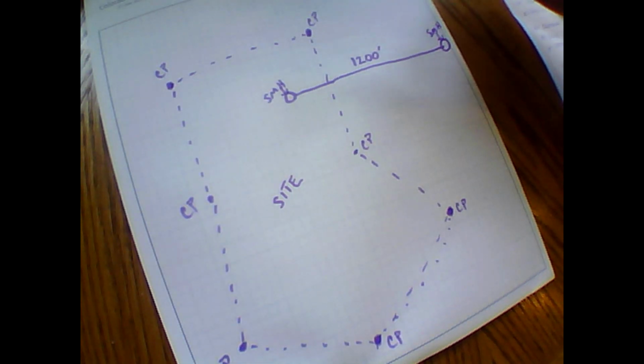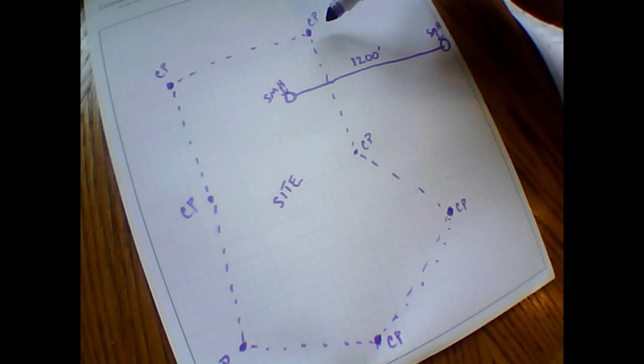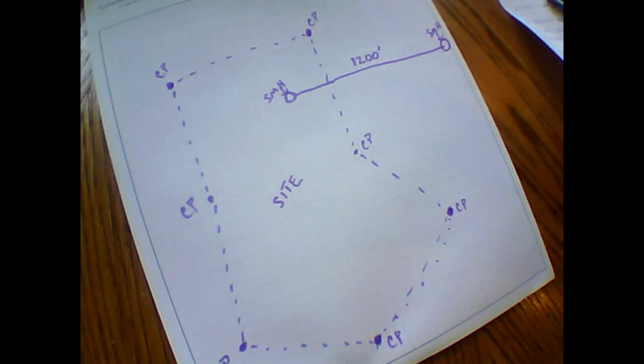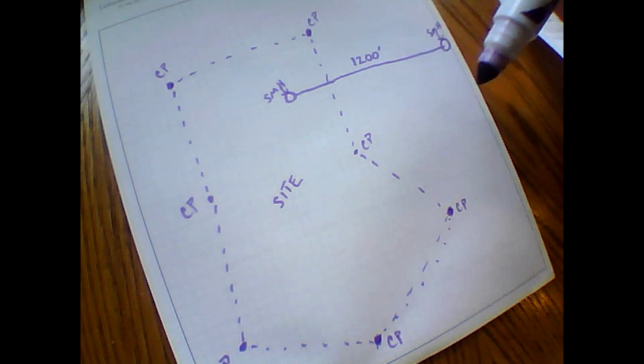So you've got your point 1000 is your shot, published values of point 1, CP1, 10,000, 5,000. You're in a no projection, no datum. That is extremely important you understand that. If you're in a state plane system or something like that, and then you add a site calibration, it's likely you'll end up with some error around the site.